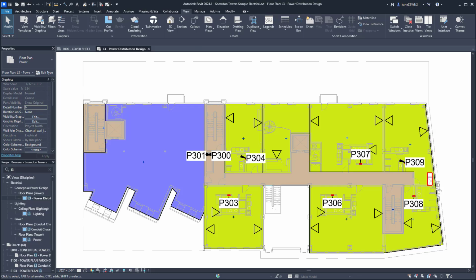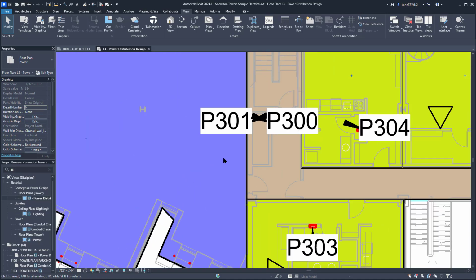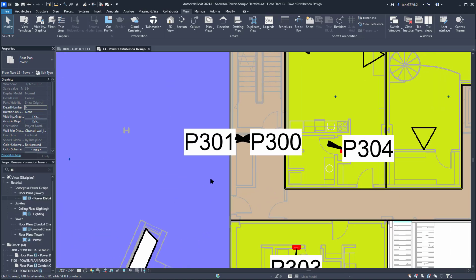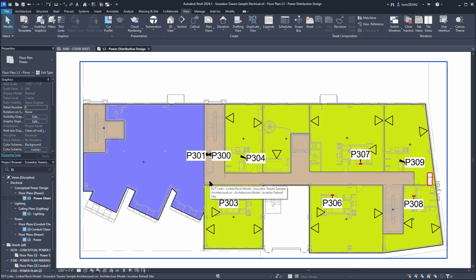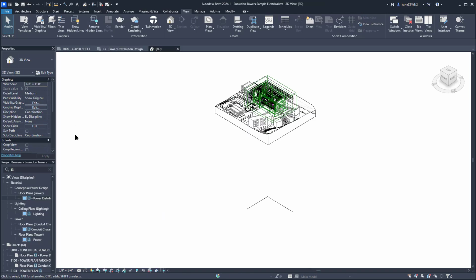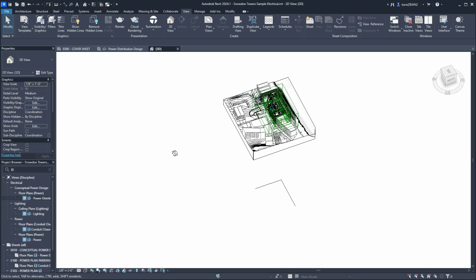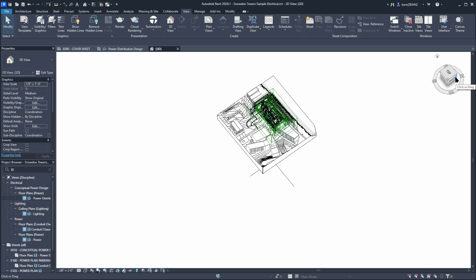By default, movement in Revit is controlled through the scroll wheel on your mouse. Scroll forward and back to zoom in and out, and click and drag to pan. You can also do a quick zoom extents or zoom to fit by double-clicking on the scroll wheel. If you're in the 3D view, you can hold down Shift, then click and drag to adjust the viewing angle. You can also use the View cube to drag the viewing angle, or to select a preset angle.